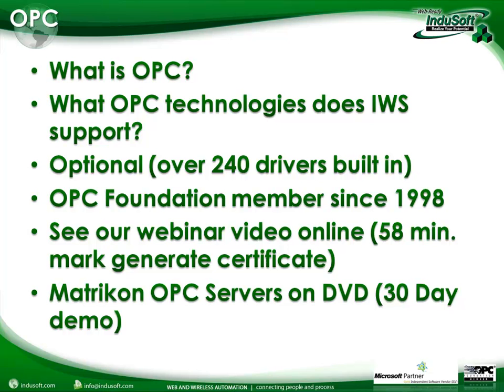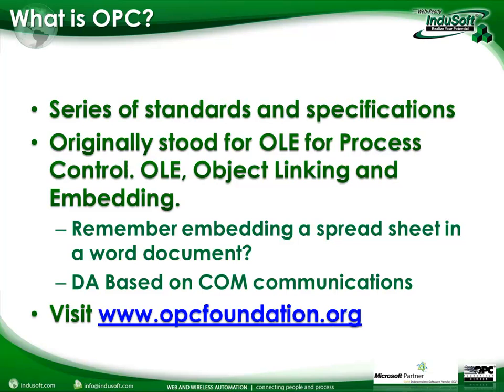So, a little bit about what OPC is. It is in general a series of standards and specifications that talk about how the communications and the interfaces work. Originally, OPC stood for OLE for Process Control. If you remember back to what OLE was, that was object linking and embedding. If you go far enough back, you can remember when we first started to be able to embed a spreadsheet into a Word document, update the spreadsheet, and have the spreadsheet in the Word document update also.